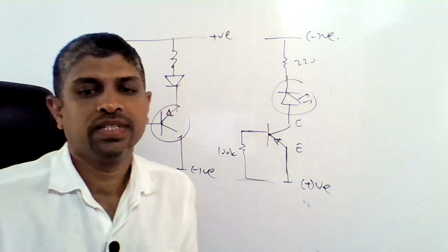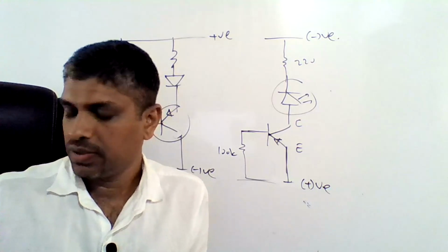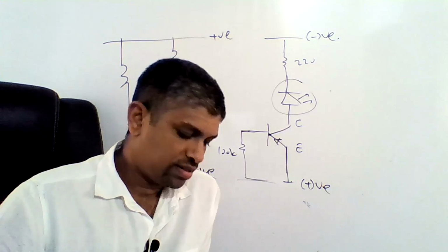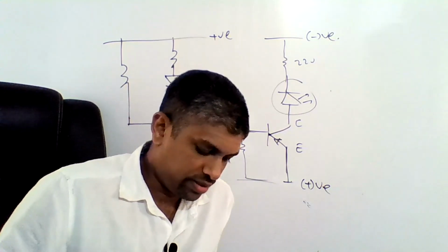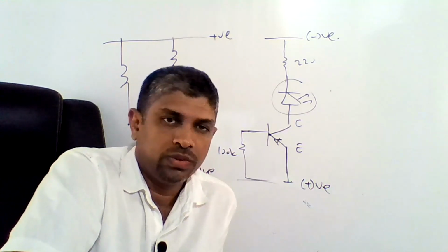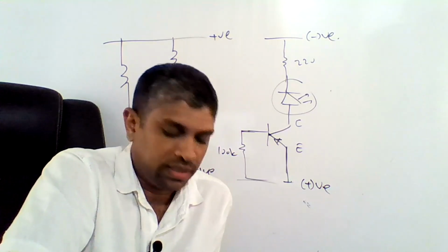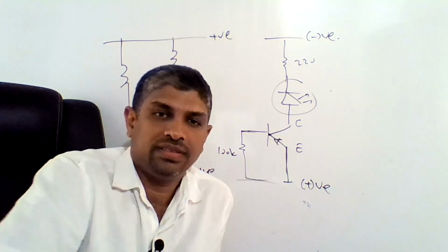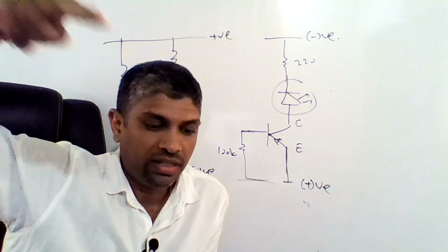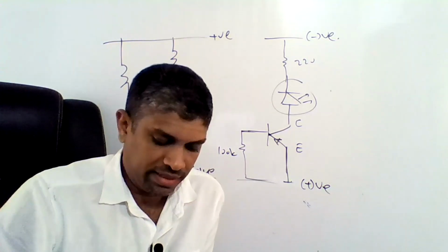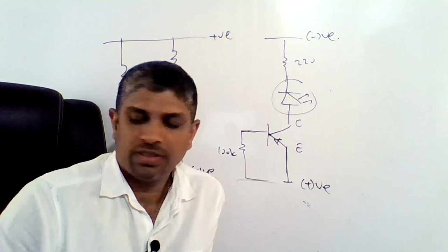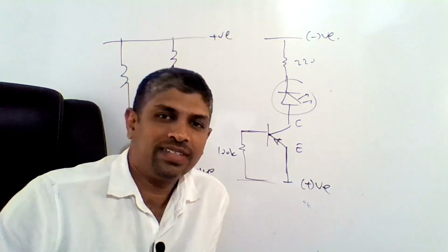Okay, so in this practical we discussed capacitors and transistors. Further about transistors, we discussed two-stage amplification or two-stage switching, as well as NPN and PNP transistors. If you use both a PNP and an NPN together, then we can maintain continuous logic. Otherwise, the logic will be opposite. That's right. Okay. So during the next practical, we are going to discuss diodes. Okay. Stay safe.